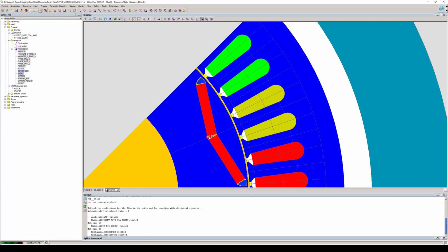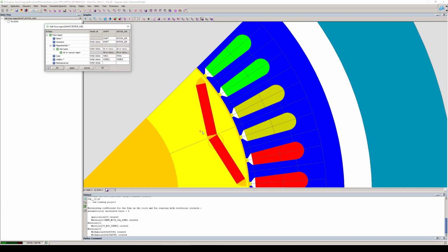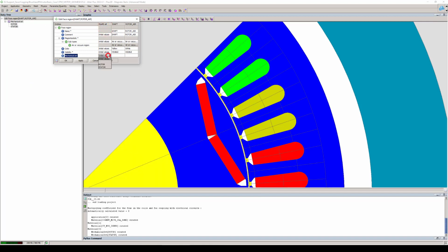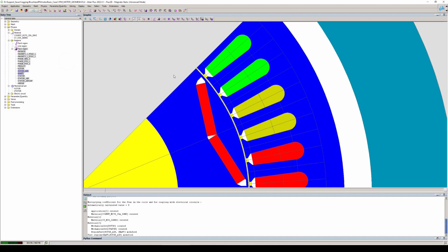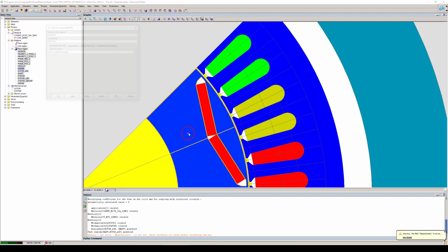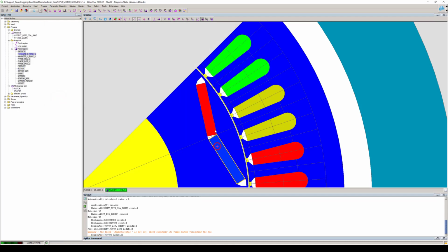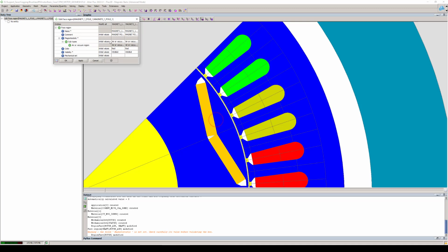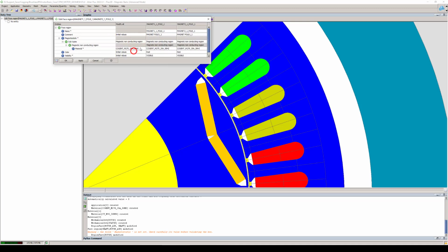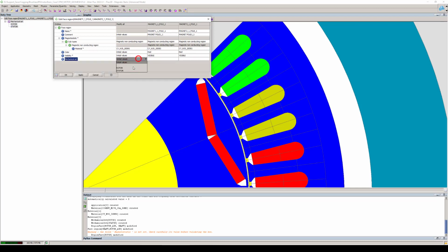So there's a lot of air region at first. So for example, on the air gap, these 2 are just air region. I can just define them as air and belonging to the rotor. Then I have my laminations here. So these will be laminated with the lamination material. I put the correct thickness and the stacking factor for my laminated material. All right. Then I have my 2 magnets. So these 2 will be defined as magnetic using the magnet material, and also put on the rotor.